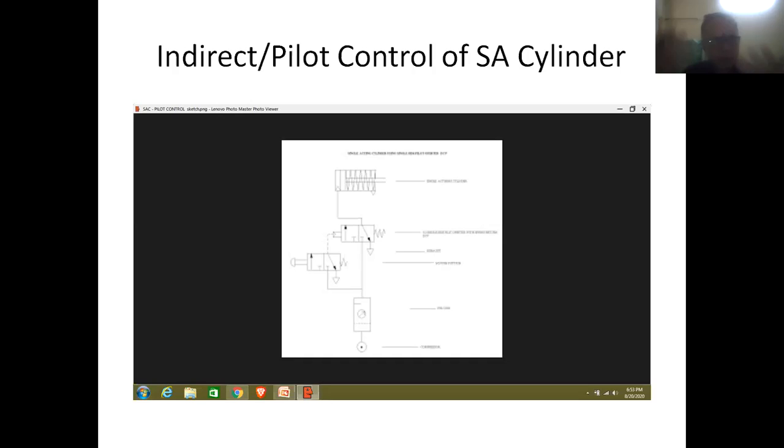So therefore, by virtue of spring action, the plunger moves in reverse direction, and the valve will be coming to second position. So my dear friends, so far as the DC valve is concerned, fluid pressure is used for putting the valve in first position, and spring pressure is used for putting the valve in second position.